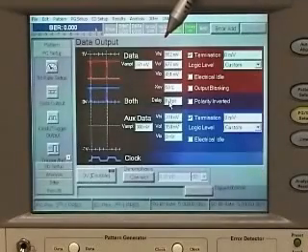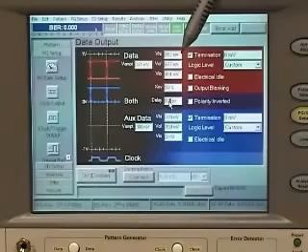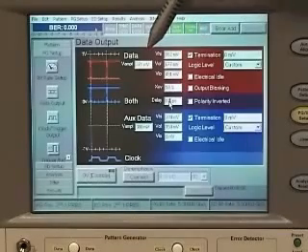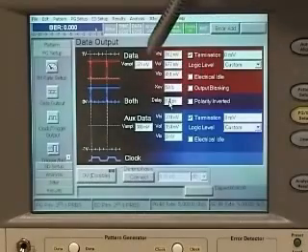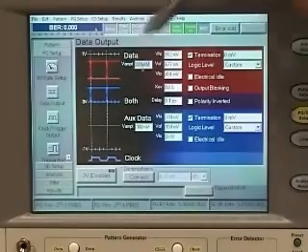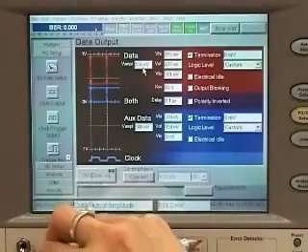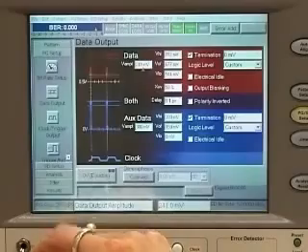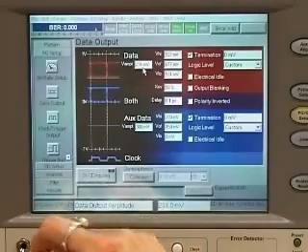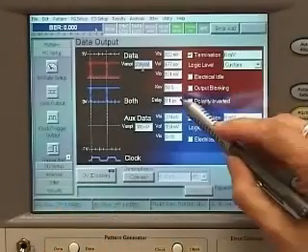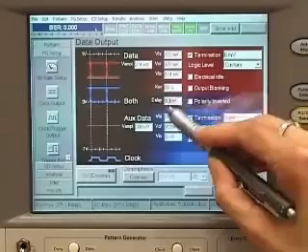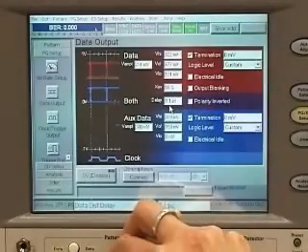So this is the new pattern generator output of the J-BERT. Here you see how you can set up the voltage levels and the offset for the data generator output and the auxiliary data output. They can be set up individually. So if you change here, you also have a graphical display of where in the voltage window your output voltage lies. You can change the delay between the data and the clock signals.